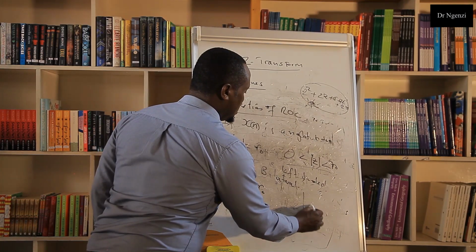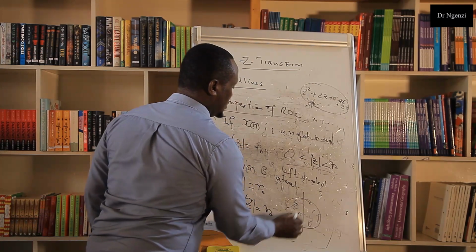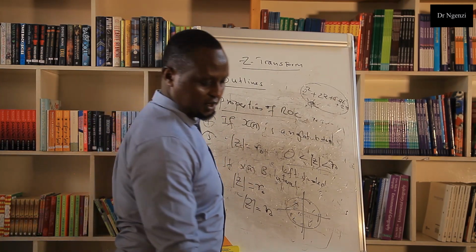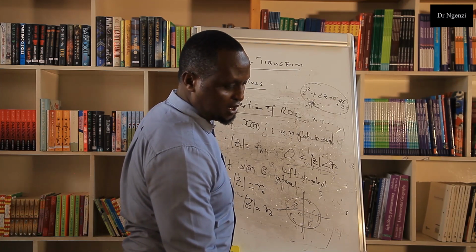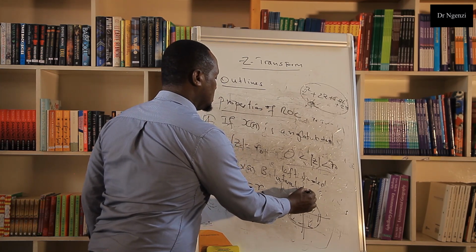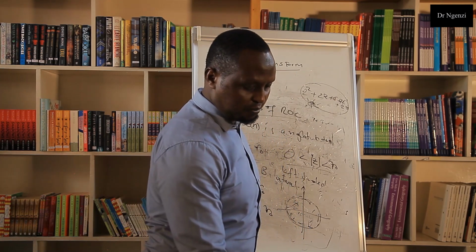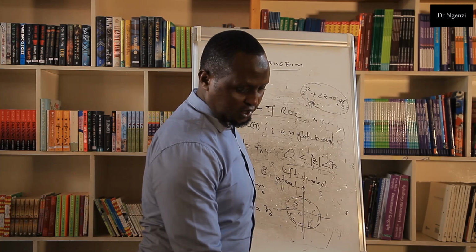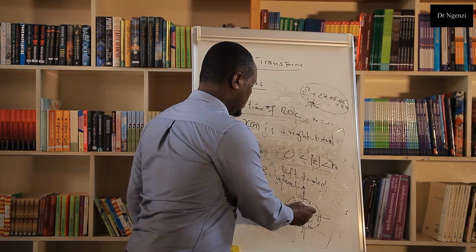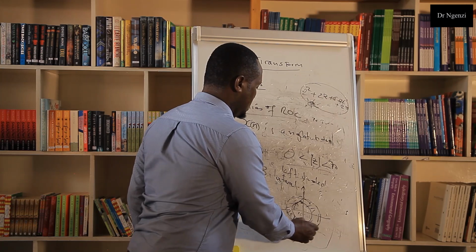So it will be the other way around. It will cover the whole side, not any limit. So it will cover the entire ring of the circle. So if it is double-sided, that's what it means. The whole of this is going to be the region of convergence. So there is no portion left behind. The entire z plane is going to have such a region of convergence. So suppose this is the center, then the whole of this is going to be the region of convergence.